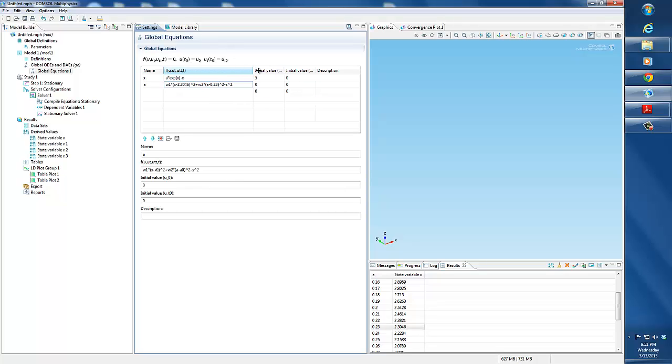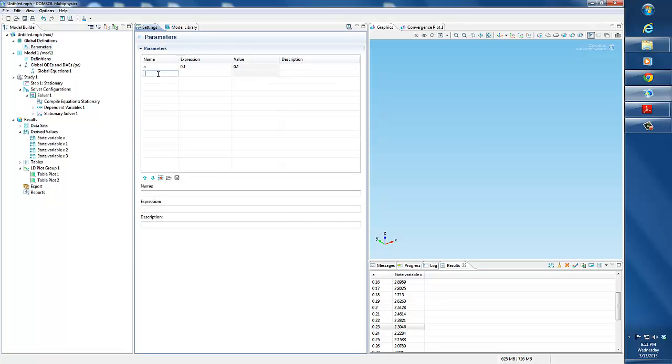Now I need to choose my weighting functions or weights for these two terms. There could be many choices, but the general idea is to make all the terms of the same magnitude. Because x is greater than these a values, we are going to choose w1 as 0.1 and we will keep w2 as 1. So let me just declare these. So w1 is 0.1 and w2 is 1, and also we need to declare s, because now we're going to carry out continuation with respect to s, which is our arc length parameter.